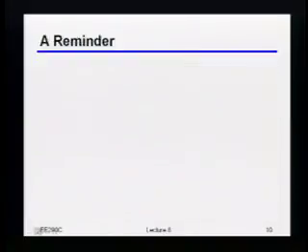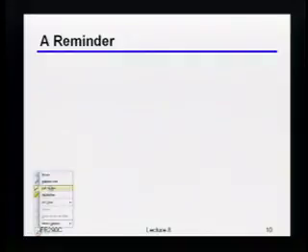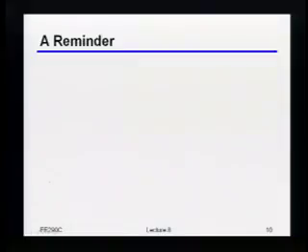It turns out we can analyze that very nicely and come up with a pretty clean expression or prediction for what that's going to do to us, both from a power and achievable performance standpoint. But before I dive into that, I just want to briefly remind you guys what sets the power consumption even for a simple resistively loaded differential amplifier, okay? Let's walk through that really quickly, because as you'll see, if you understand this, figuring out the performance of the DFE and what's achievable is also pretty easy.